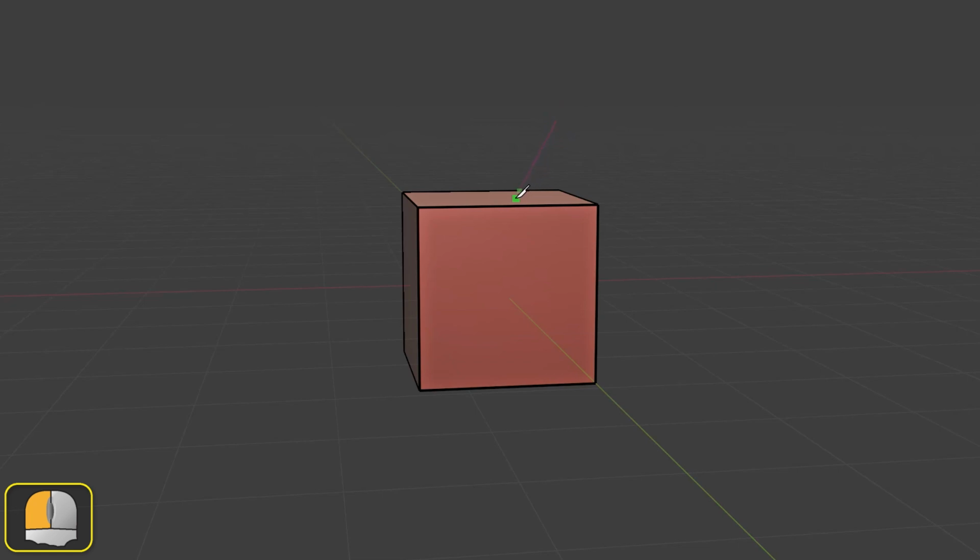Blender shows a marker where the new vertex will be placed, though as we move the knife, the marker moves too. But when we pass the knife over the second and subsequent edges, the point we pass through finalizes the locations of the first and second vertices. All the points we have passed the knife through will become new vertices when we complete the operation. If we finish the cut in the middle of a face, we need to remember to left-click to fix that point. Otherwise, the final location will be ignored.